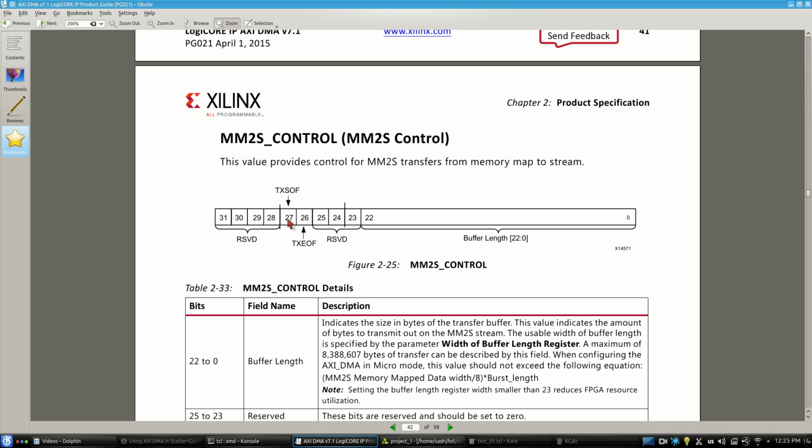So when a descriptor that I have written to the block memory is responsible for, in fact, transferring the initial part of a packet, in fact the heading chunk and some data after the header, this flag is set. This is 1, this is 0.